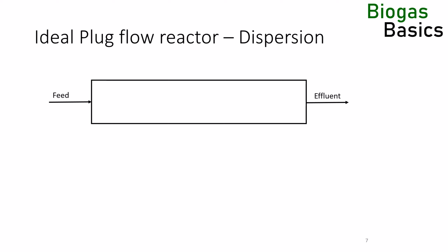The second reason why it is de facto impossible to build a plug flow reactor in AD is axial dispersion. What is axial dispersion? Dispersion is mass transport due to concentration gradients, amplified by mixing and velocity gradients usually generated from external energy input. Dispersion is similar to diffusion, but diffusion relies only on random molecular movement and is generated without external energy input. Both effects can be described with Fick's laws. In AD reactors, the dispersion coefficient is much higher than the diffusion coefficient.